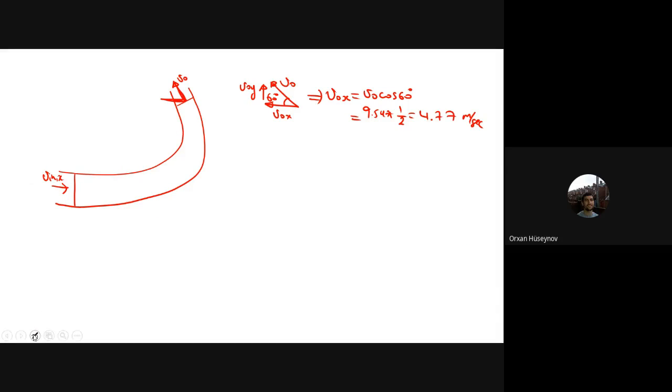Now I'm going to use the Bernoulli's equation here. So it will be P by rho plus V squared by 2 plus gZ for inlet, should be equal to P by rho plus V squared by 2 plus gZ for outlet. But in the energy equation, there is no need to worry about the components because it is a scalar equation. Since it's a scalar equation, no need for components. But the momentum equations are vector equations, therefore you should write the components. Let's start one by one.